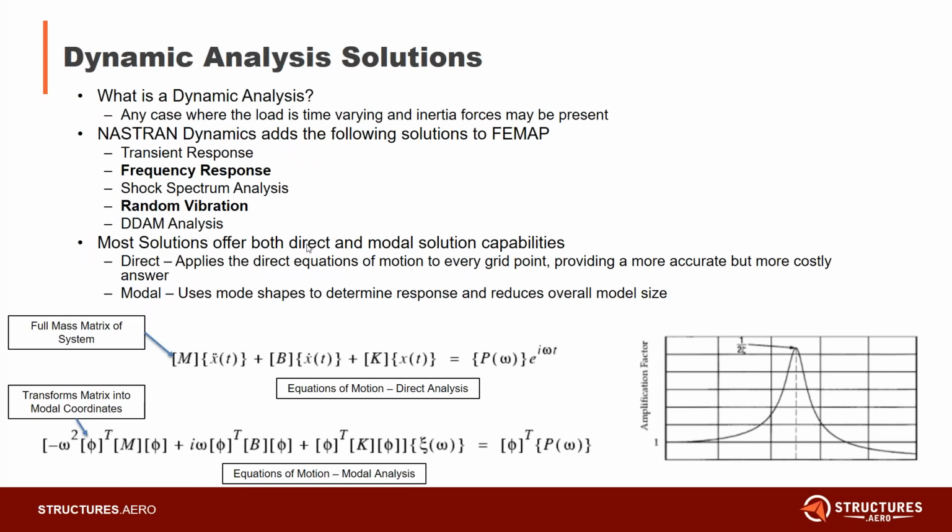So first of all, what is a dynamic analysis? It's any case where your load is going to be time varying and you might have inertia forces present due to that time varying load. Just to show down here on the right side, we have a graph of your typical loading as you near a certain resonant frequency for a single degree of freedom system. Many times in statics, you might apply a load and you might end up with just a response of 1. But if your load is time varying and happens to couple with the modes of a structure, you might result in some amplification, as shown here by this brief graph.